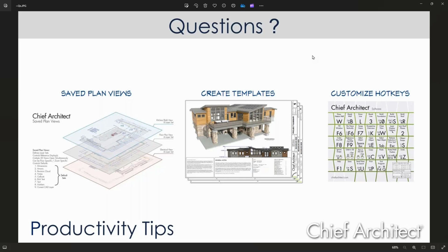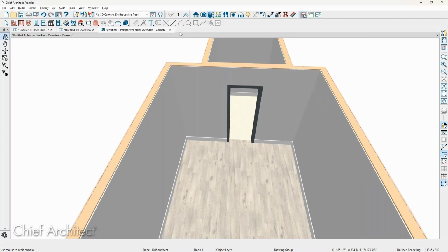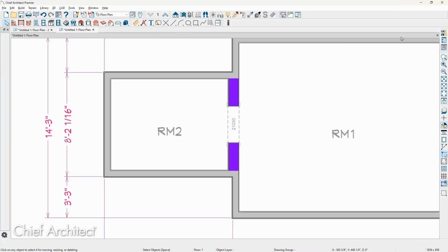Hey, Scott, quick question for you. One of the callers was asking about multiple buildings on the same site, and you referred to using a reference display to show them both. Could you go over that briefly? How would you go about doing it? So reference display works when you want to show a floor above and a floor below. And you can also point it to an as-built.